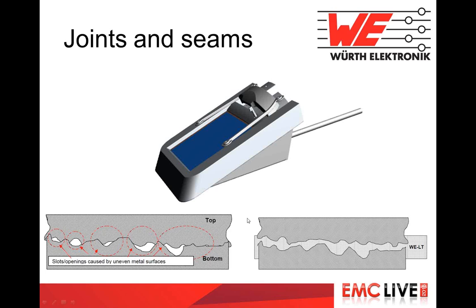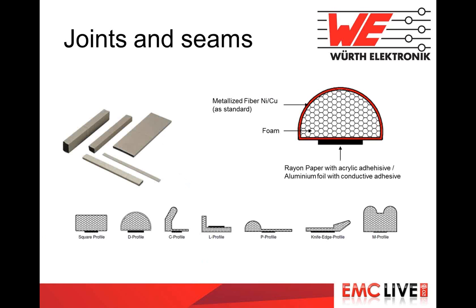They're called gaskets. You will find them in almost every electrical device. Gaskets are conductive materials that fill the space between both sides of the joints and the seam to provide conductivity all along the connection. There are many kinds of gaskets, and all of them use the same principle. They have a core material that gives the flexibility to adapt to the joint or the seam, and then a highly conductive surface to provide a continuity path so the electrons can go through the aperture and don't generate any electrical field.